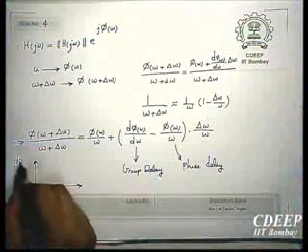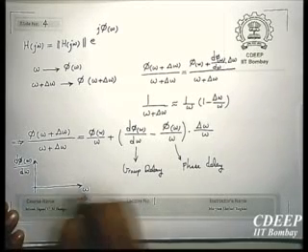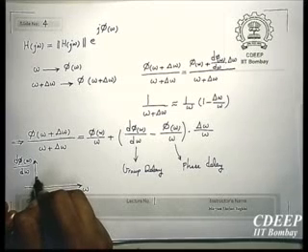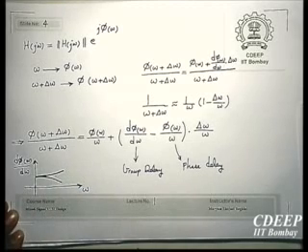So what you want to do is, if it is d phi omega by d omega, and this is omega, you want to make this almost constant. Usually it is like that, or it is like that, and this depends on the order of the filter. Now in continuation we will see, for example, filters like Bessel filters, which use Bessel functions, get very nice phase characteristics but not magnitude characteristics.